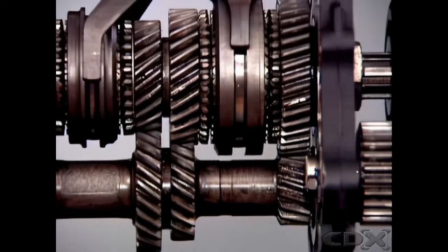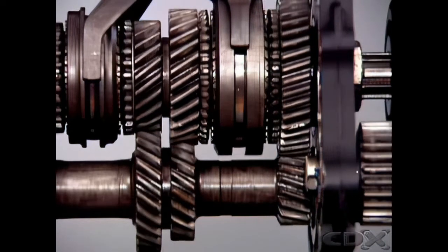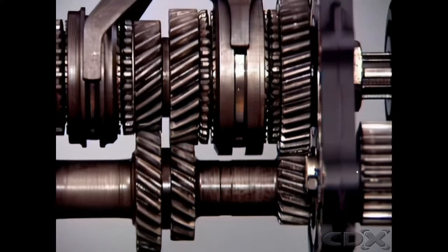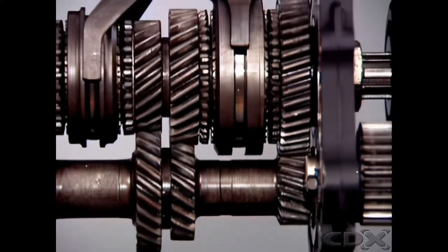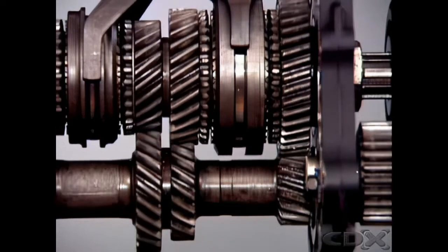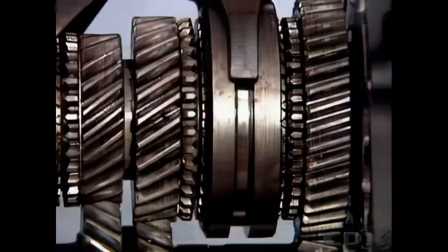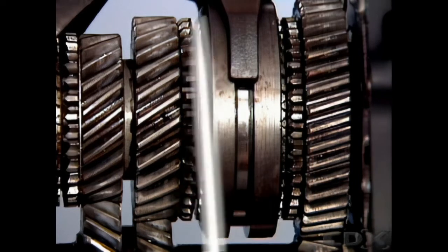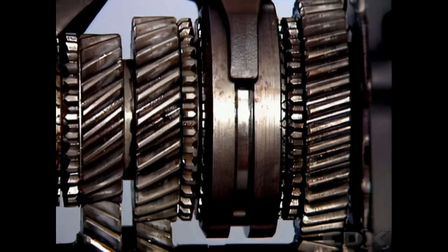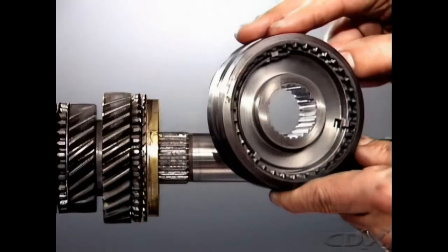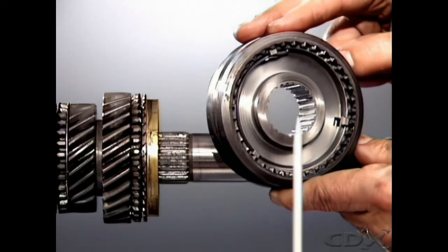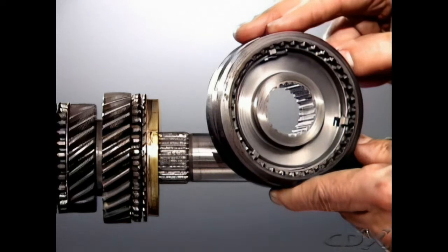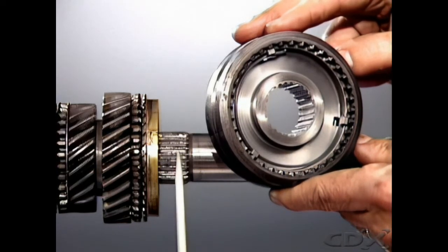These gears mesh with mating gears on the main shaft or output. These main shaft gears are supported by bearings on the shaft. They can rotate without turning the output. Each main shaft gear has an external tooth section on one side. The teeth face an internally toothed engagement sleeve located on a central hub, which is itself splined to the main shaft.